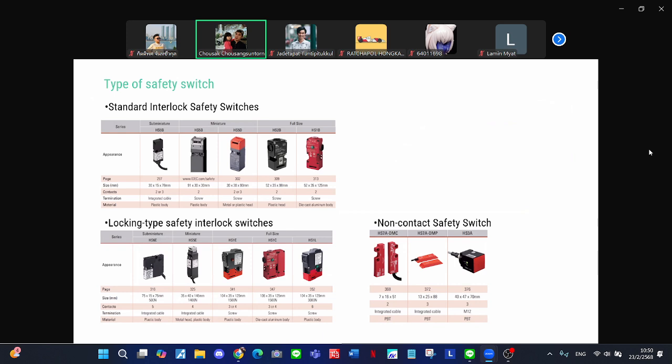Okay. Sometimes workers need to go into the dangerous area to perform maintenance. In this case, the safety interlock switch on the door should be an open circuit, to reduce the risks in the system. We also have a locking type at the exterior for protection, stopping the machine from running if the door is opened, to prevent unnecessary shutdown when the machine is safe to use.